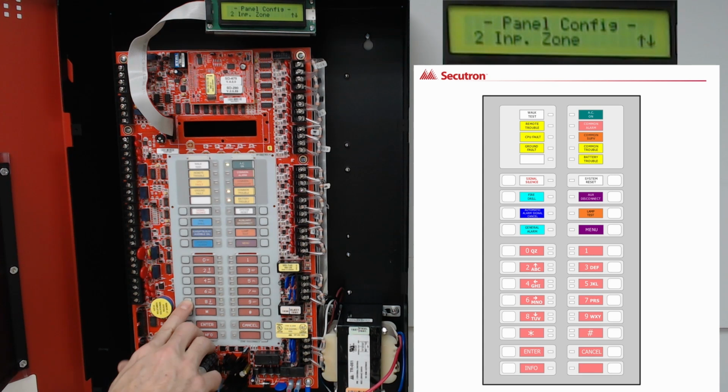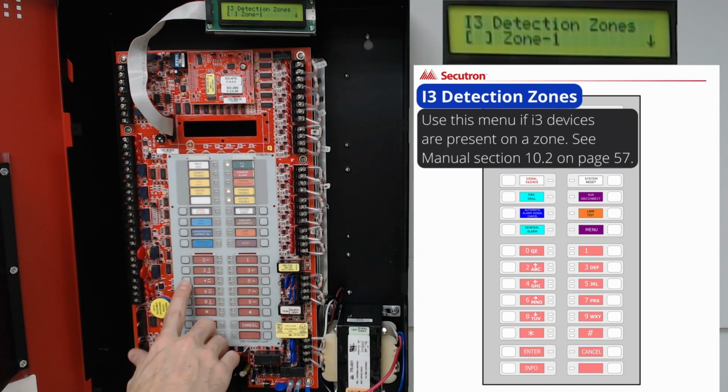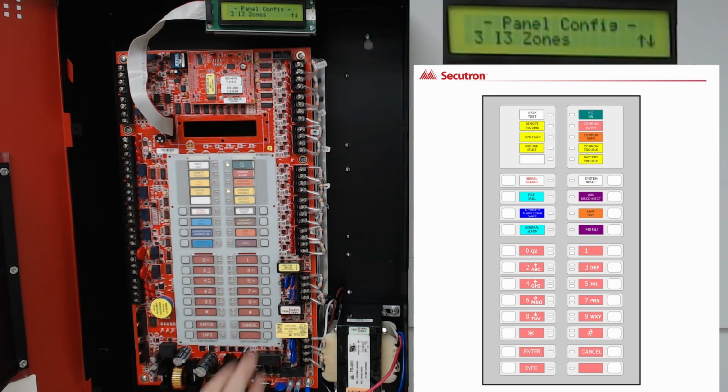By pressing down, I can see my next option, which is my I3 zones. By pressing enter, we can then go and enter into the I3 detection zones. By pressing the left or right cursors, we can apply the X to identify that there are I3 devices in that particular zone. And the zones will be 1 through 12. Again, we hit the left or right cursor arrow to indicate that there is an I3 device present in that zone. By hitting cancel, we exit back out to the previous menu options.